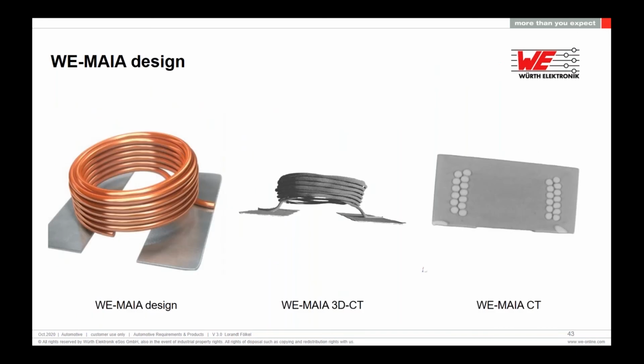During manufacturing, we first make this air coil. This is a wire-made air coil. Then we put this air coil in the tooling together with the powder, and we press them together, and that's it. It is not a sintered material. The air gap is a distributed air gap inside this metal alloy. It has excellent saturation. In fact, on the smallest volume, it is the best inductor which can be reached.